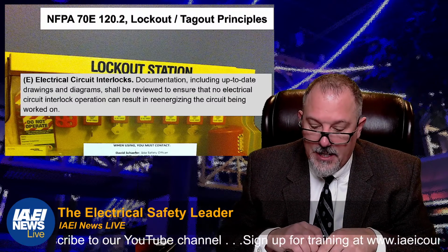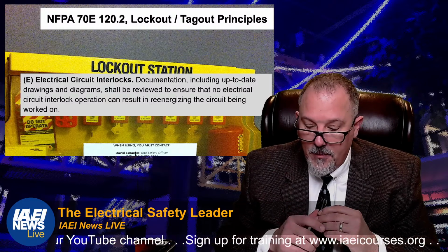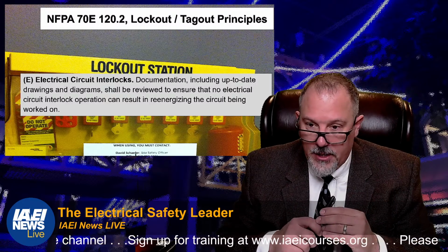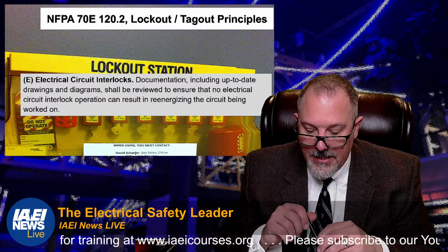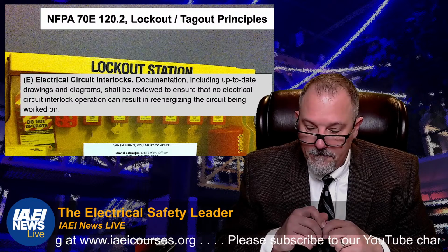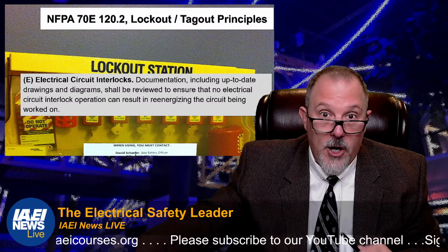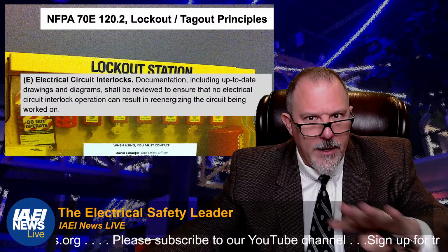Documentation, including up-to-date drawings and diagrams, shall be reviewed to ensure that no electrical circuit interlock operation can result in energizing the circuit being worked on. Not in. You don't want to be in the circuit. You want to be working on the circuit.